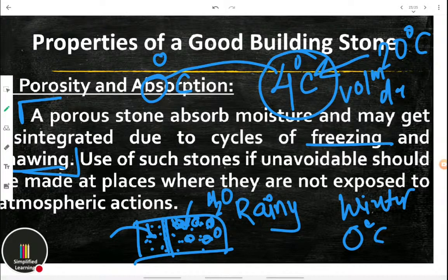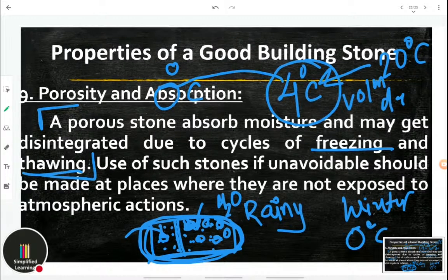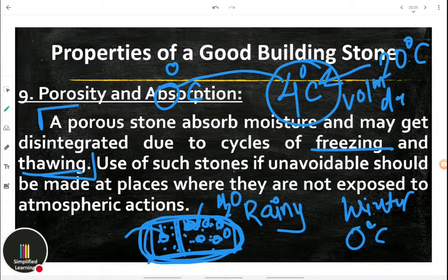The water is going to expand inside the pores, expand inside the cavities, and because of that, the water, which is now ice, will be exerting a tremendous amount of pressure over the stone structure. And what will happen when a stone is stressed? Obviously it is going to break, it is going to disintegrate. That's why porosity and absorption should be as low as possible when we are going to use the stone